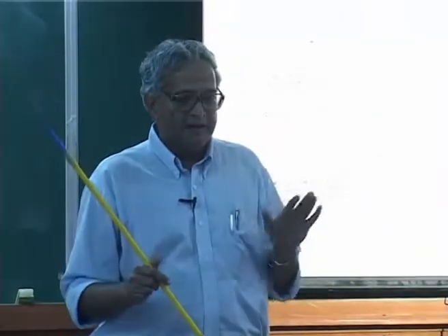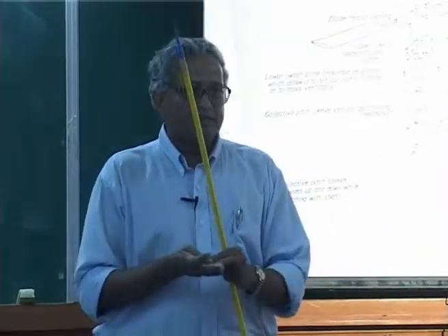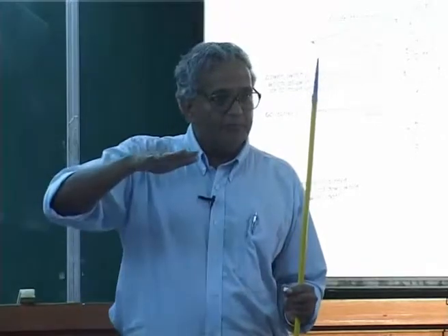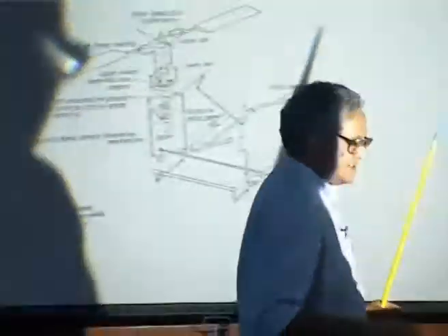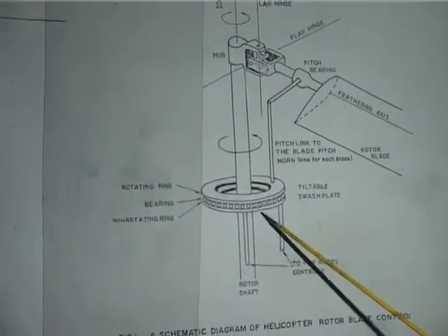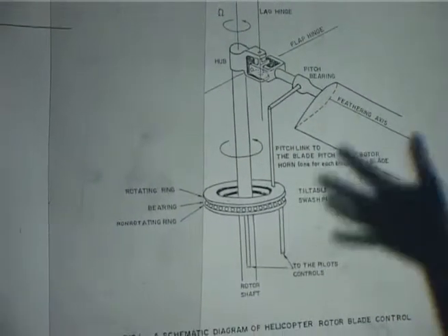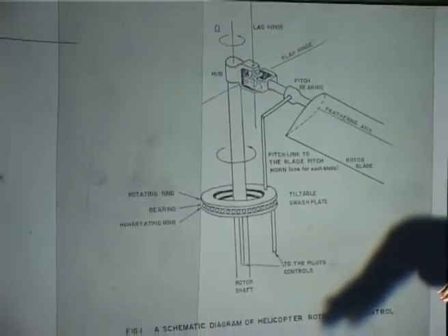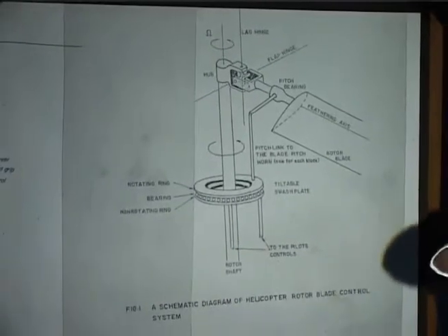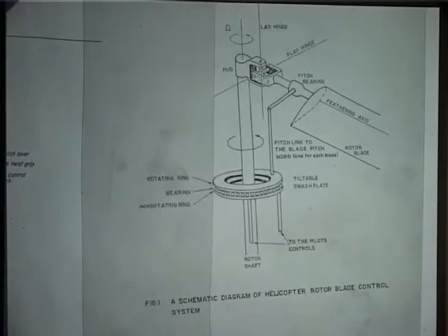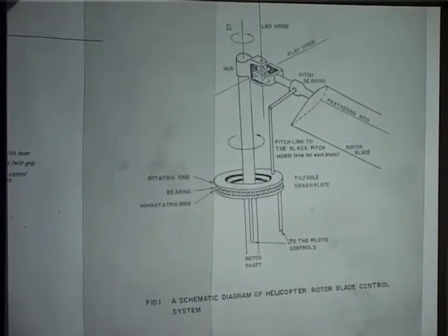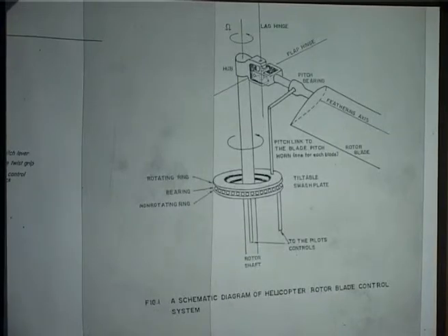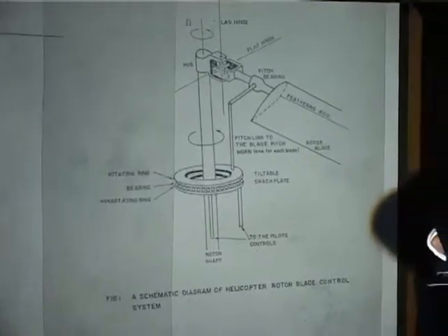I will say there is some rigging done. At present we will not bother about the rigging. What it does is, instead of moving up, the swash plate will tilt, like this. You can now tilt it in any plane, please understand. Let us assume it is tilted about some axis and it is tilted like this.